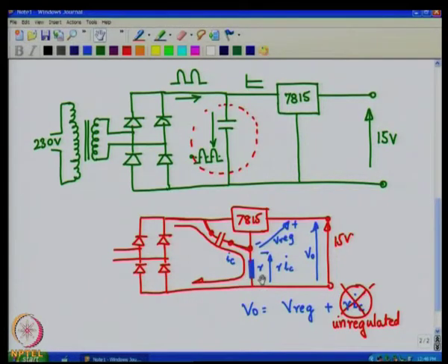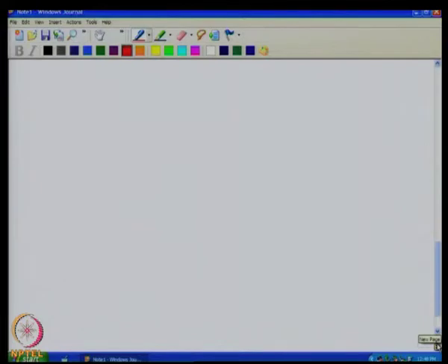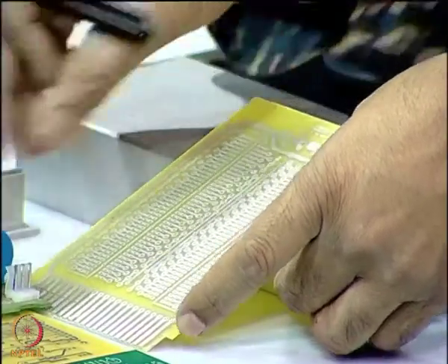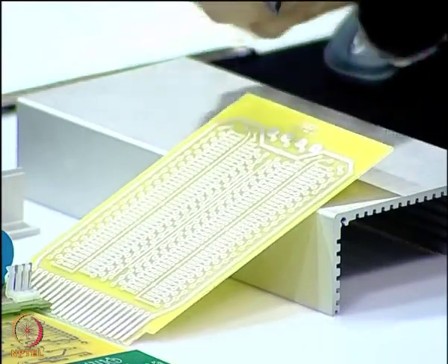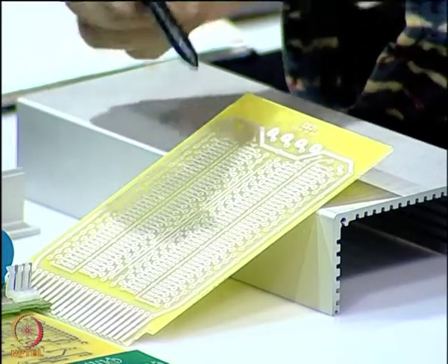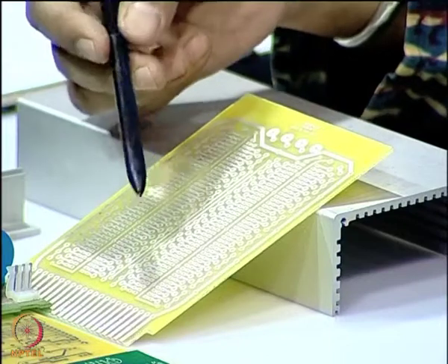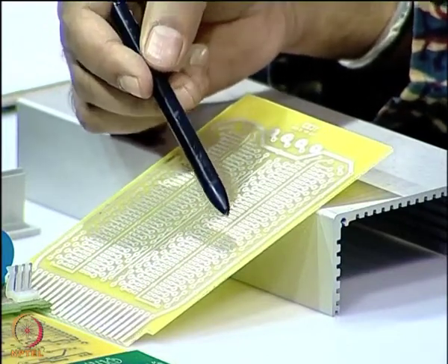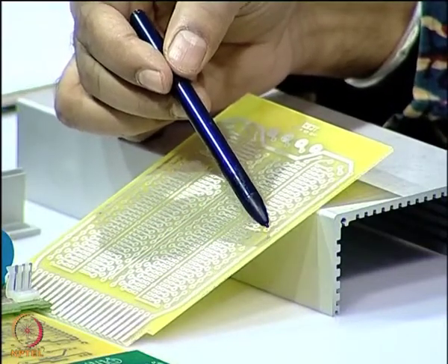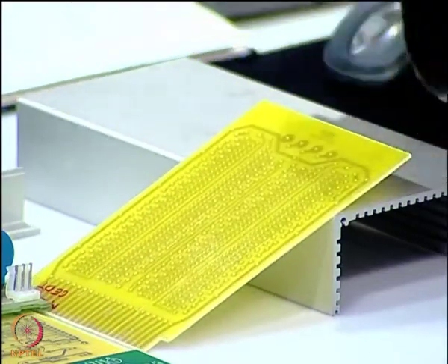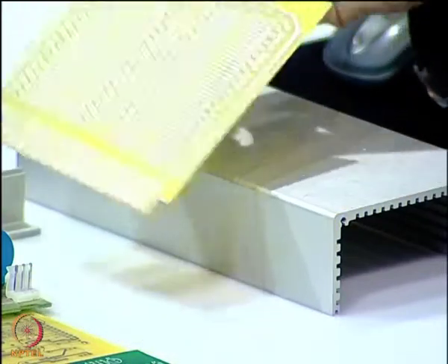Let us look at the resistances a bit more closely. When we take up the PCB track, for example, now if I look at the board here, you see this board. Now, if you look at this board, you see it is made up of many tracks. It appears silver, but they are all copper tracks, and on that they are tin plated to prevent the oxidation of copper. So, these copper tracks have finite resistances. This is a single sided board, there is nothing on the back.